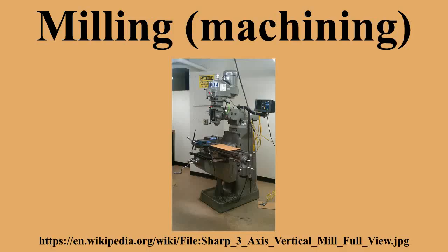Gang milling. Gang milling refers to the use of two or more milling cutters mounted on the same arbor in a horizontal milling setup. All of the cutters may perform the same type of operation, or each cutter may perform a different type of operation. For example, if several workpieces need a slot, a flat surface, and an angular groove, a good method to cut these would be gang milling. All the completed workpieces would be the same, and milling time per piece would be minimized.